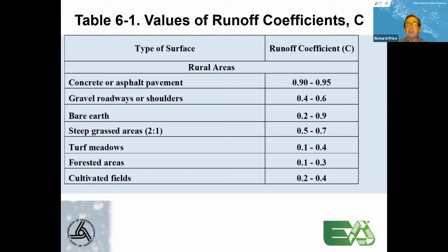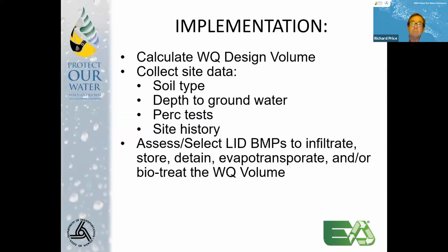It's important that you design for the total volume that you're going to receive. And this often includes water from outside the right of way, because if you only design for your project area or for the DOT right of way that drains to your discharge point, in a larger storm, the additional water from off-site is going to overwhelm your BMP and may cause erosion issues and any number of problems with that.